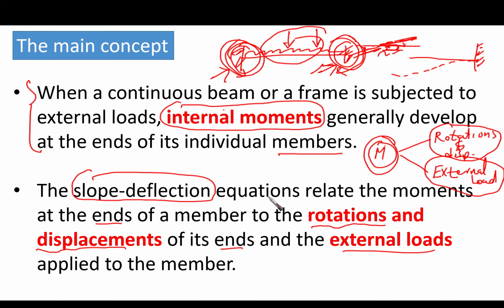The slope deflection equations relate the moments at the ends of a member to the rotations and displacement of its ends and the external loads applied to the member.